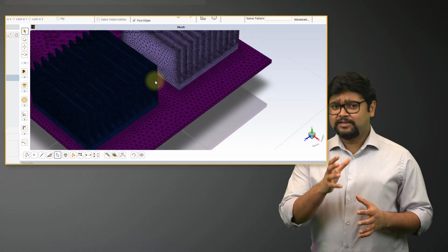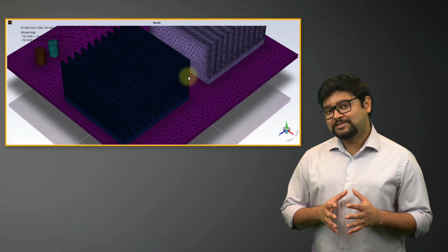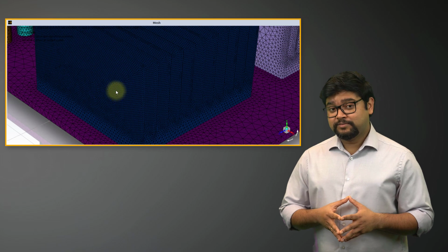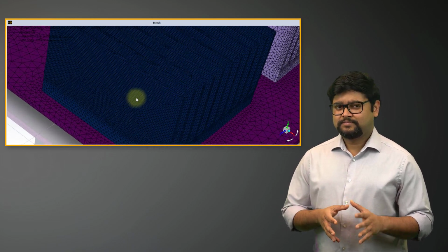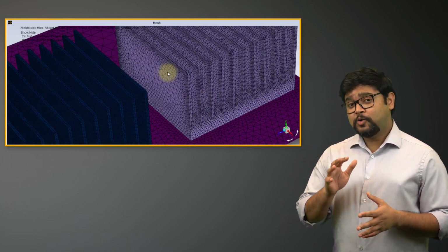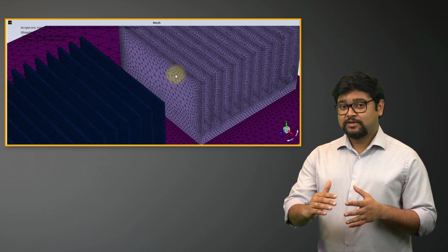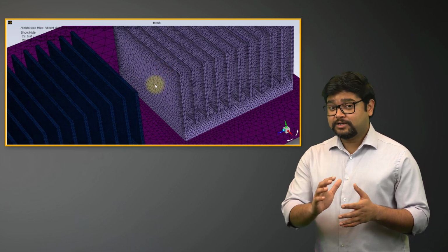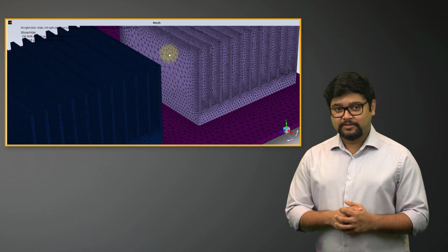You can clearly see the effect of scoping the local sizing to edges compared to faces by comparing the surface meshes on the two heatsinks. The local sizing is applied only at the edge of the face, where the size of the element increases while moving away from the edge where the sizing is being applied.